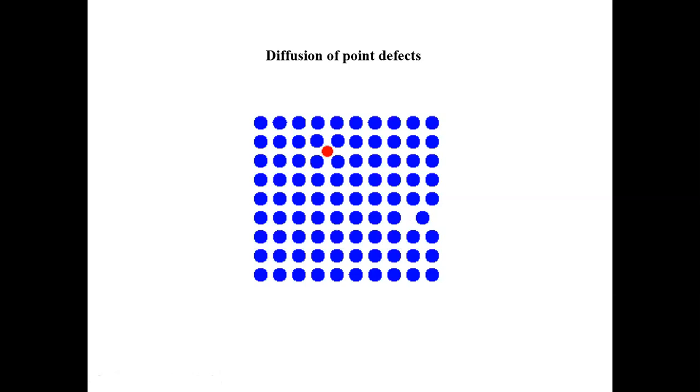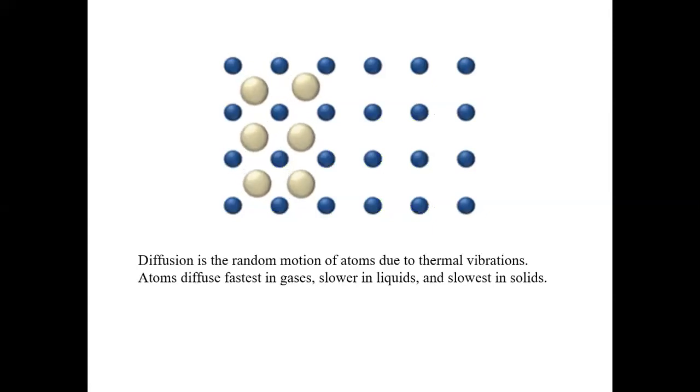And self-diffusion is always due to the vacancy diffusion. So we're going to describe all these types of diffusion in solid state in detail. But here it's just to give you a very rough intuitive picture of what's going on. So now let's start with interstitial diffusion, which is the easiest to treat because this wouldn't change the underlying lattice. So this is the most simple analog to the liquid state diffusion.